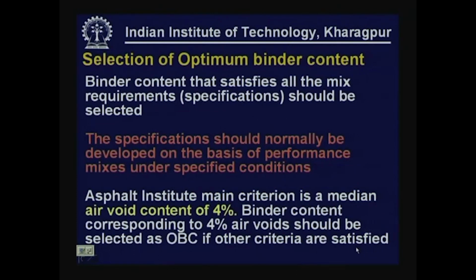So, for selecting the optimum binder content, we normally have to select a binder content that satisfies all the mix requirements, that is specifications given by a given agency. These are to be selected. The specification should normally be developed on the basis of performance of mixes under specified conditions. So, we believe that whatever specifications are given by MORTH or Asphalt Institute or other agencies are on the basis of observation of the mixes and about their performance under varying conditions.